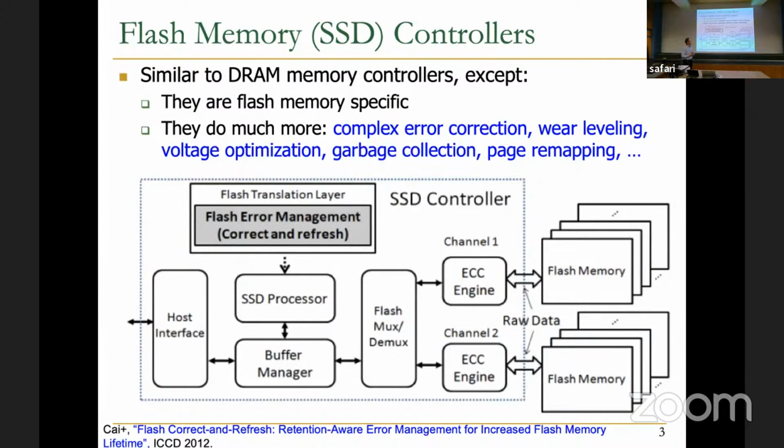So what do they do? They try to do wear leveling. They try to ensure that none of these flash memory rows wear out in a disproportionate way compared to other flash memory rows. So they try to level the wear, or level the writes, across all of the flash memory rows. Everything fails at the same time, hopefully. That basically makes things more manageable, let's say. So they actually do wear leveling somewhere over here, which is not shown over here.